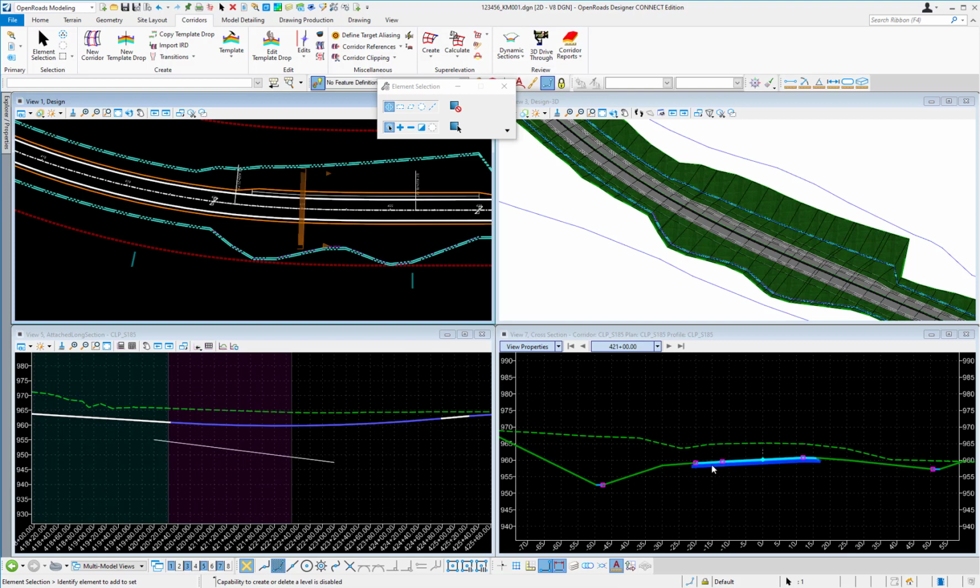so the edge of pavement elevations, or edge of pavement points, were being controlled by point controls for the super elevation. As we work through it, we widened the left shoulder here, so now we have a point control on our left shoulder. We also have one for the left ditch line that we moved. For our right ditch line, we also have one here.